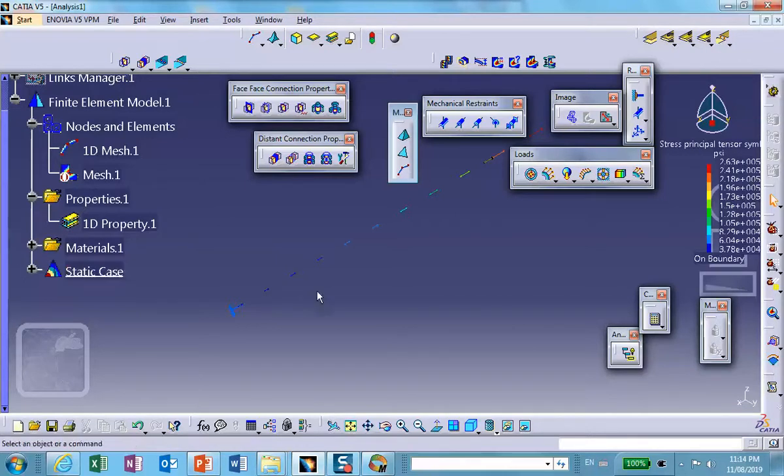What this means is that actually that factor should be flipped. Because the intention was for this end to have a small cross section, large stress, and for that end to have a big cross section and therefore small stress. So this factor, I need to flip it.